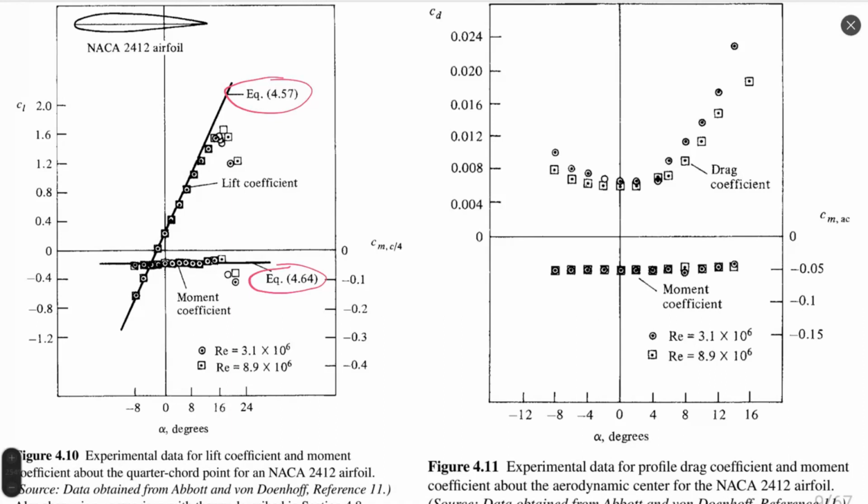So we need additional knowledge of how this function will behave, and we take this knowledge by analyzing similar airfoils. We already see that for NACA 2412 the function looks parabolic, so I expect that for airfoils similar to this we will also have parabolic behavior of the drag coefficient.